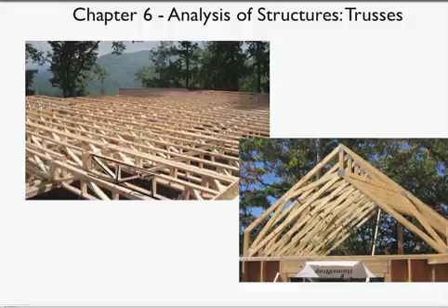And so you've got a whole bunch of individual short pieces put together in some fashion to make a larger overall piece. The advantage here is that this is called engineered lumber building, and you don't have to have a really large chunk of wood, which you'll find out in mechanics of materials and later, because you can get the same sort of bending resistance, the same tendency not to sag when you put weight on top of it, by building it this way.